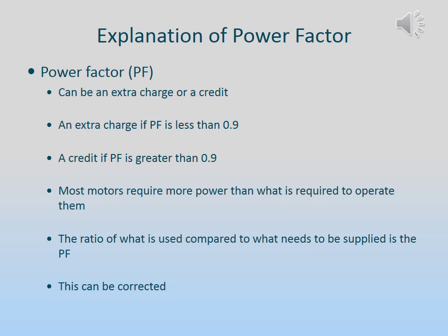If we lower the amperage more than 5% and we increase the power factor 5%, then our formula says we are going to save energy. We are not saying a power factor correction is always going to save us money. It depends, but it will lower your amperage draw, and this will allow your motor to run cooler. If the motor runs cooler, then it will last longer.